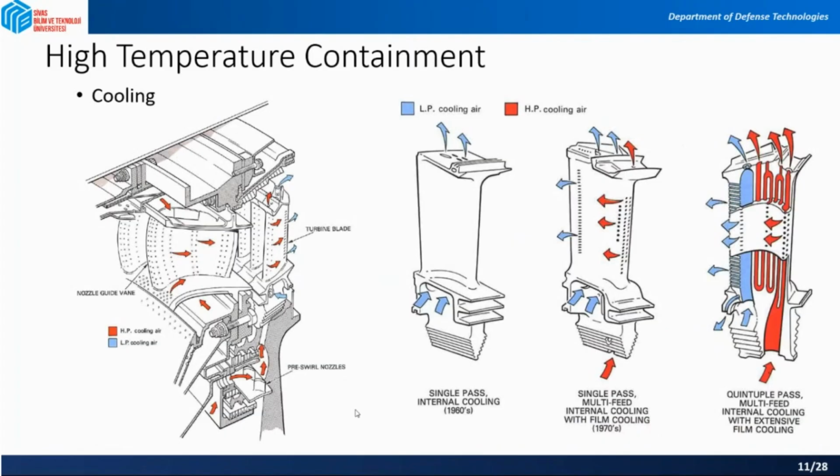The turbine vane and turbine blade life depends not only on their form that we were discussing from a single crystal casting, but also on the method of the cooling. Therefore, the flow design of the internal passage is very important.